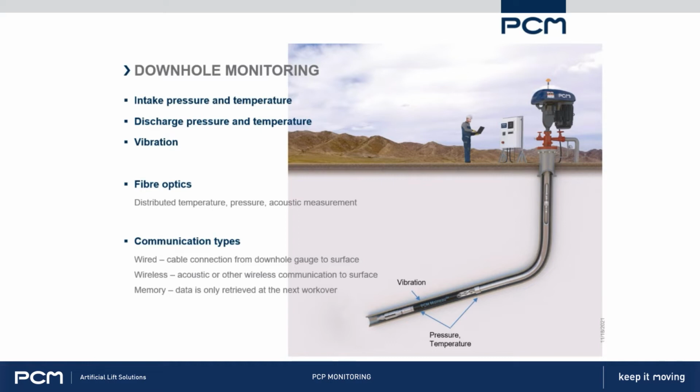Downhole monitoring is usually intake pressure and temperature, discharge pressure and temperature, and vibration. The companies that make these gauge packages just include the vibration on there whether you need it or not, so it's something that's available if you're buying downhole gauges.